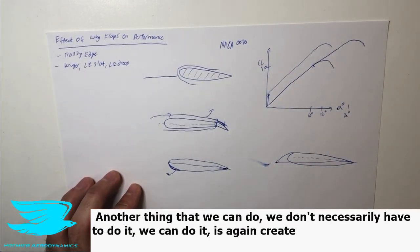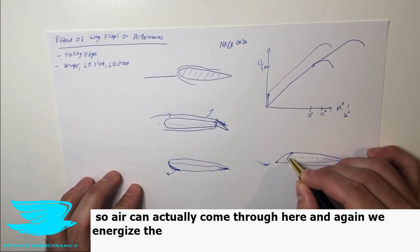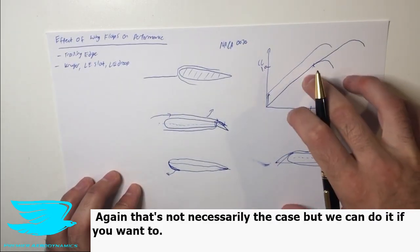Another thing that we can do, we don't necessarily have to do it, but we can do it, is again, create a separation between this Kruger flap and the rest of the airfoil. So air can actually come through here and again, re-energize the boundary layer and keep the flow attached even longer. Again, that's not necessarily the case, but we can do it if we want to.